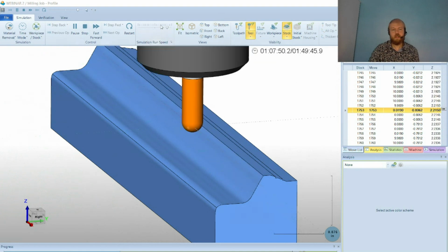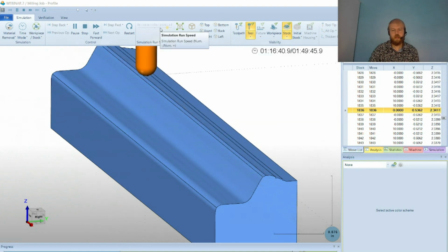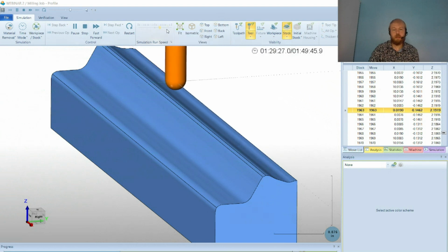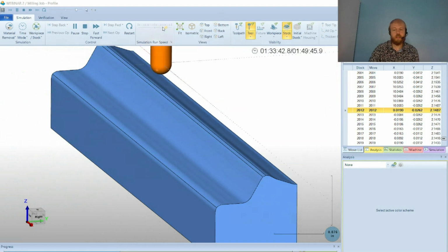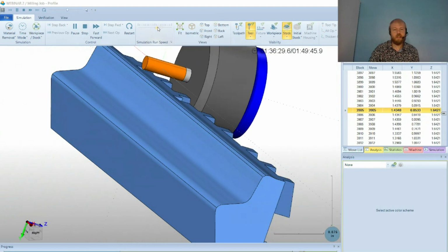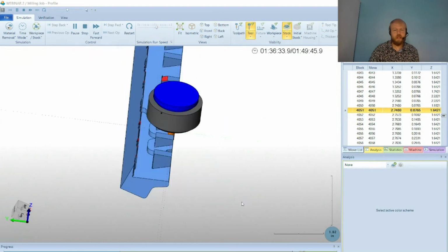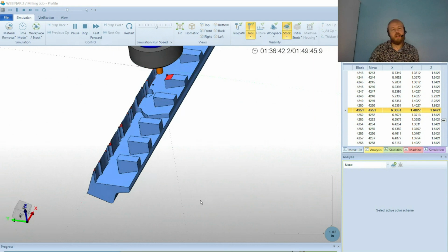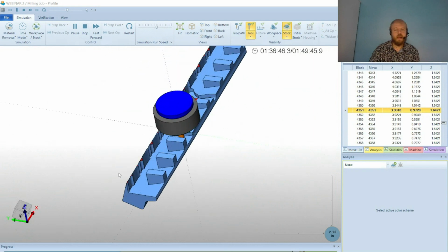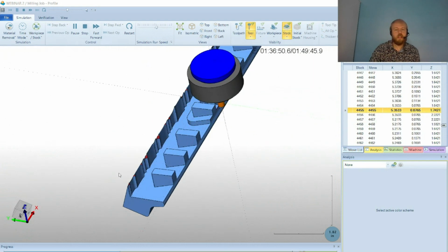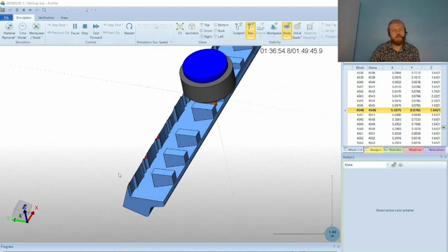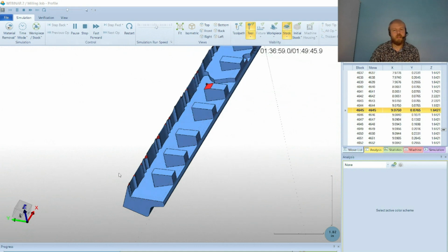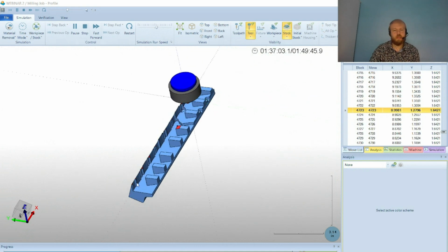So here's the roughing and finish first on this side. Then it would put a stop in the program for us to refixture at a different location. Again, this is 3-axis because it doesn't get all the way past, does it? But anyway, this is 3-axis where we can refixture it. We also have the 4-axis where we can change the index locations as well.